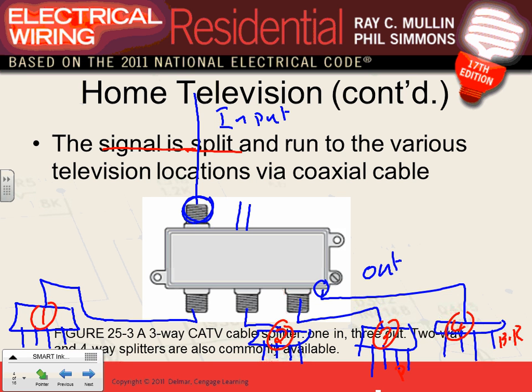Can I have thumbs up, Chad? And what you bring here is a coaxial cable. You guys have seen a coaxial cable? You have the inner core of the coaxial cable that carries the signal. Around it, there's a shield that protects the signal from being corrupted by the surroundings. So what do you do? You ground the shield as you enter the building, and the inner core, the conductive material, is what carries the signal, and you land this one at your receiver, wherever your receiver is.